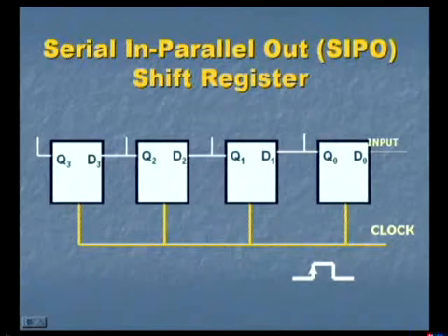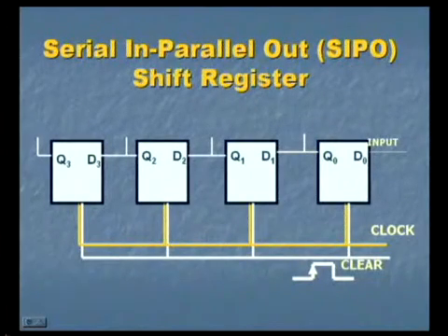register. It has a clock pulse and a clear signal. For example, we take a 4-bit register that requires 4 flip-flops. At first, the clear pulse is given that makes the content of all these flip-flops 0. At a later time, the input is given to the first register, that is the serial input is given from this flip-flop, and parallelly the output is available at all the flip-flops.